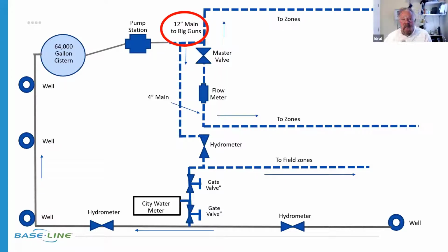So we're using some sensors that are placed in the cistern. It's a Watertronics pump station, and they're providing a signal to our event decoders. At a certain level of inches inside the cistern, we're turning on the wells to start recharging. The wells can almost keep up with the smaller turf stuff.